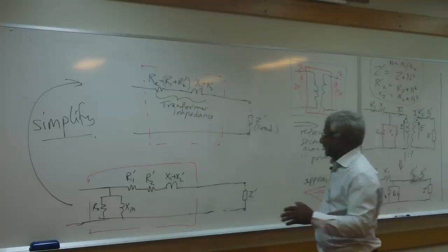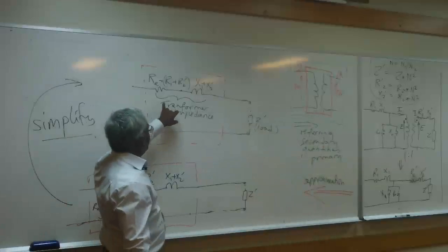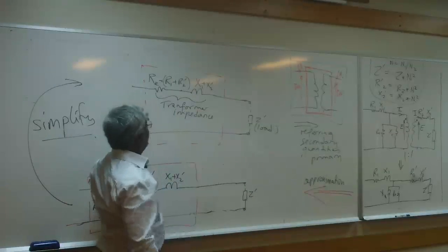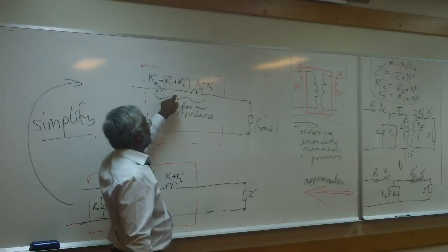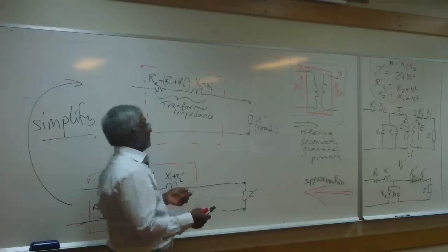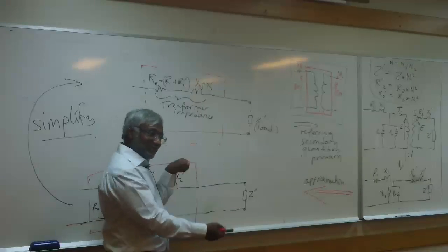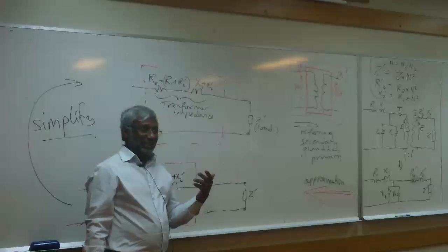Okay, so we get to here. You can measure that using the short circuit test. By the way, I kept that separate because in practice you tend to measure that by measuring the winding resistance separately. So in your test plan, you would have separate measurements of those two, because that can be done with DC.